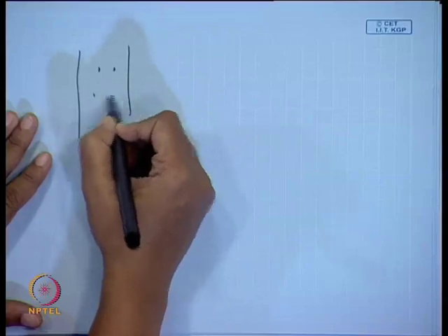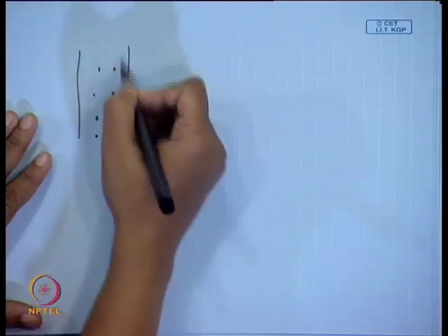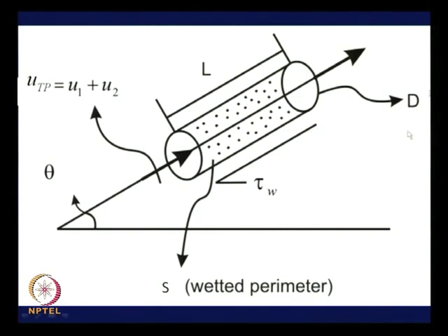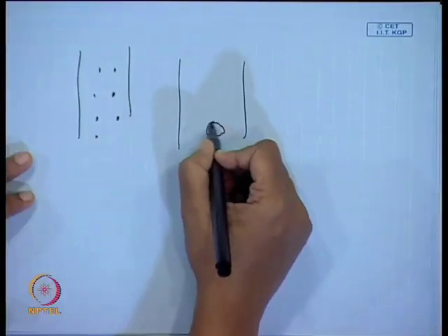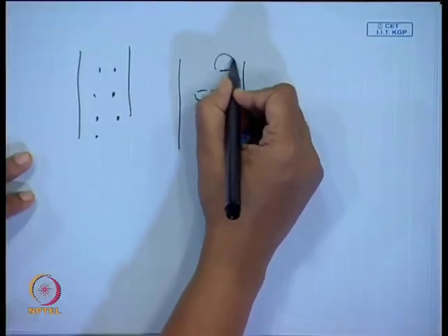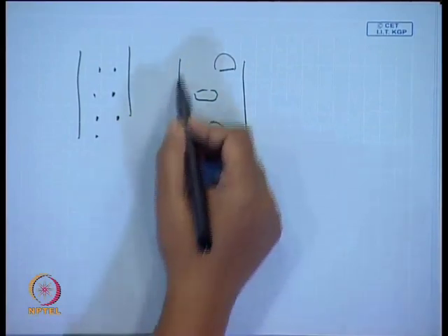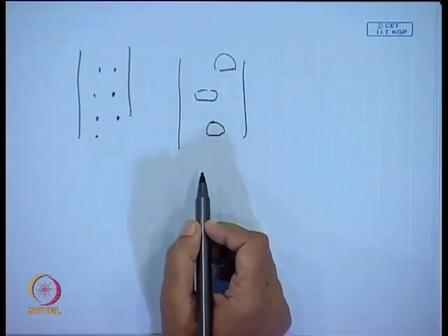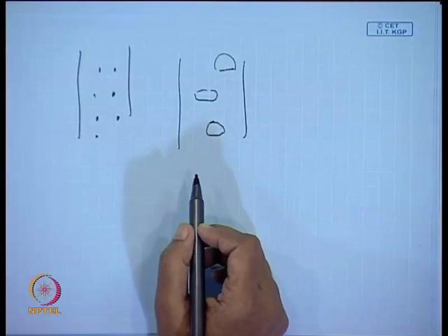That means the entire thing has this particular appearance; this is the correct picture. The moment the bubbles become larger and get deformed, the uniformity goes away. Under this condition the homogeneous flow model does not strictly apply, but we apply it, see how much deviation there is, and then suggest suitable correction factors.